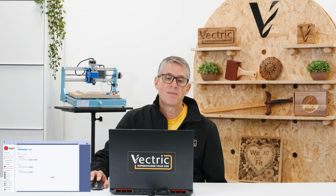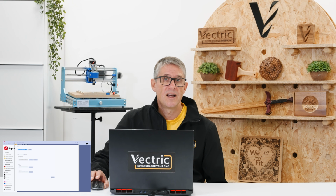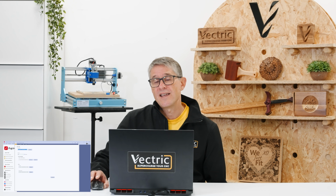So what you do with this template is you're creating essentially a single file which has in it the sheets of material that you're typically using for, say, your cabinet projects. So it details things like the dimensions of your sheet material, what material type they are, and other properties of that material. It also includes a full list of the toolpath strategies, as toolpath templates, that you're likely to apply to different sorts of geometry that comes in from your cabinet design package. And then the last thing it does is also set up the nesting parameters.